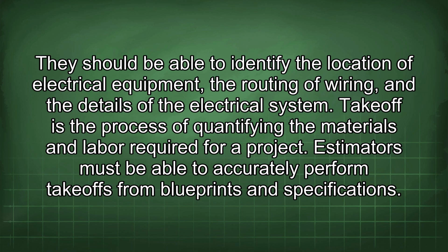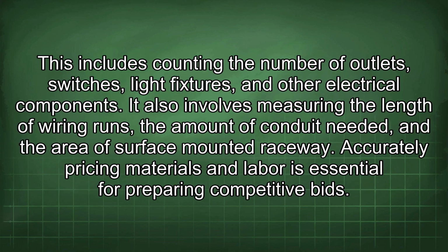Estimators must be able to accurately perform takeoffs from blueprints and specifications. This includes counting the number of outlets, switches, light fixtures, and other electrical components. It also involves measuring the length of wiring runs, the amount of conduit needed, and the area of surface-mounted raceway. Accurately pricing materials and labor is essential for preparing competitive bids.